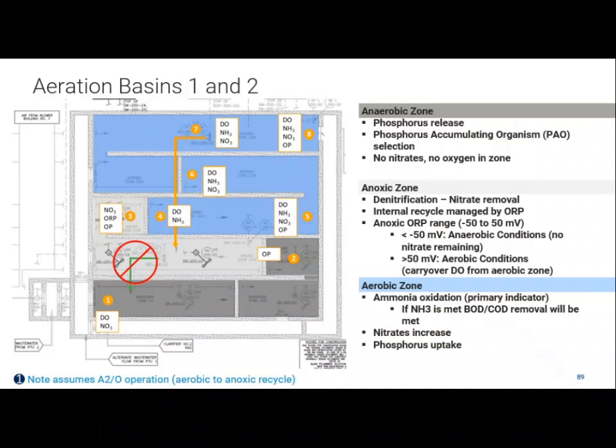Yeah, you're trying to see how much denitrification you had here, right? If this nitrate number is really high leaving the anoxic zone, what does that tell you? If there could be some oxygen, what else could happen if there's nitrate leaving the zone? Not an inhibitor. Go along the same lines of the oxygen. What do you need to remove nitrate?